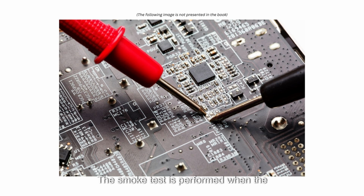The smoke test is performed when the populated board is being powered up for the first time. This requires monitoring of the lab equipment's voltage and current meters, to ensure that the board can achieve the desired voltage levels and current draw, while initially using a power supply in a current-limited mode.